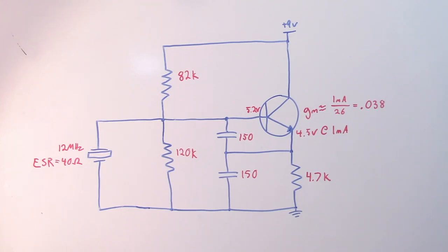But that doesn't really matter too much, because what we're really concerned with in terms of the crystal parameters is that internal resistance, RE, because that shows up in all the equations that we've been working with. However, that's not specified in any datasheet anywhere ever. Unless you're working very closely with the crystal manufacturer or you're sitting down and measuring each crystal, you're not going to know what RE is.